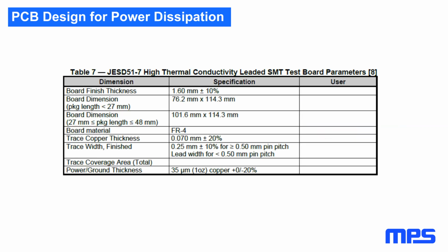Unfortunately, the thermal resistance number is heavily dependent on the PC board construction. The numbers you find in datasheets are all based on some standard construction. Usually a JEDEC standard called JESD 51 is used. JESD 51 has several types of standardized board construction. The one most commonly used in IC datasheets is JESD 51-7, which is shown here.